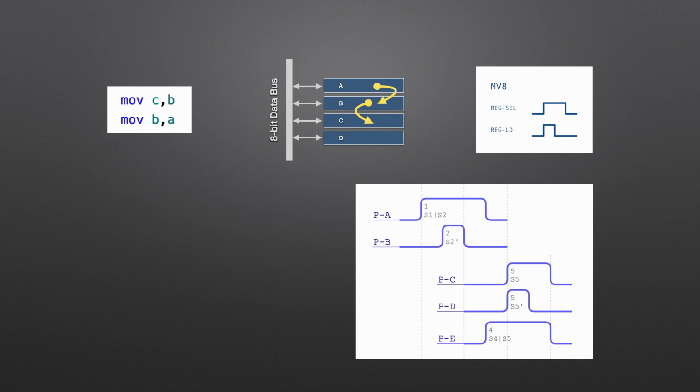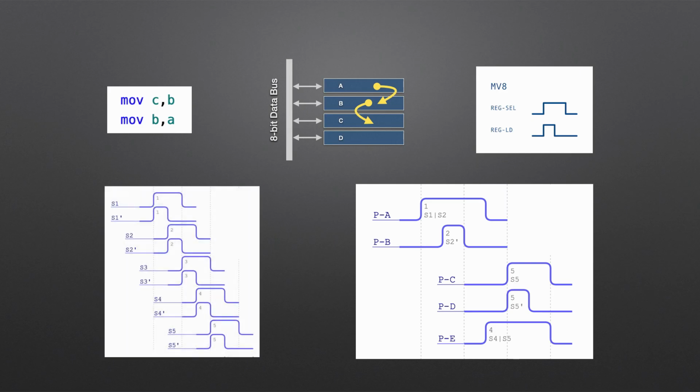So, I guess you're thinking, that's all fine, but how does the sequencer produce these pulse shapes, and will all this madness ever end? The answers to which are finite state machine and no, this madness will never end. In the simplest terms, the finite state machine's job is to count. Its outputs look like this. Now this might look a bit confusing, but effectively it'll produce numbered pulses in a set order. Pulse 1, then 2, then 3 and so on.